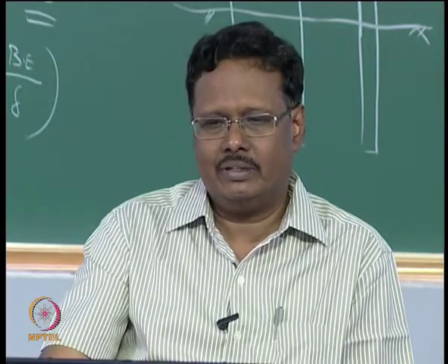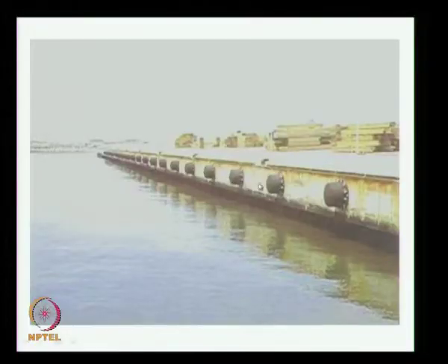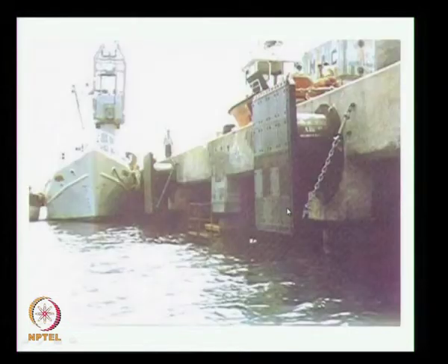These are some of the fixtures that will be adopted. You are seeing the fixtures also. In this particular slide, you can see the lowest water level is here, and how they have fixed the highest water level. These two levels are the bottom of the fender and top of the fender, and how the chain is connected. When the vessel is touching the water, there is so much freeboard, so it is not required that the bottom of your fender goes right up to the low water level, but you can see the shape of the vessel. So only in the middle portion of the vessel will the berthing be taking place.